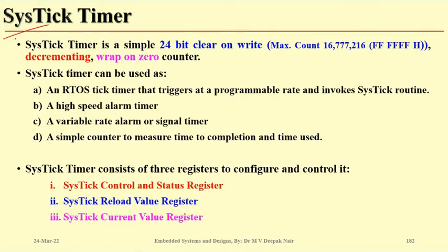First of all, we will talk about the SysTick timer. We can say system timer also. This is the system timer which is connected to the microcontroller directly, the crystal which is connected to the microcontroller. The SysTick timer is basically a simple 24-bit clear-on-write, decrementing, wrap-on-zero counter. So what are the features here?